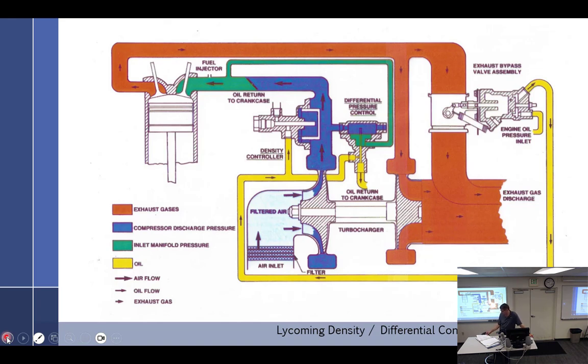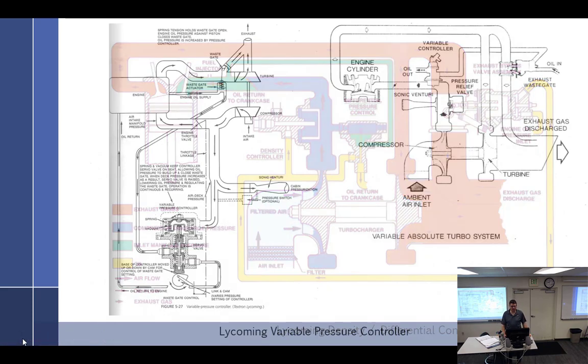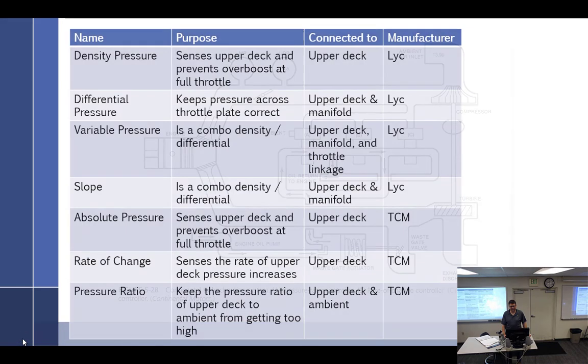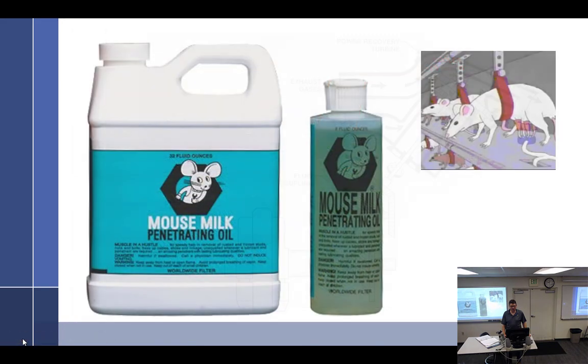When is ice most likely to happen in a carburetor? What operation of flight? Landing or idle. Low power, landing or idle.